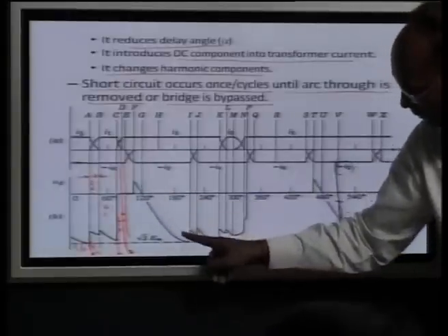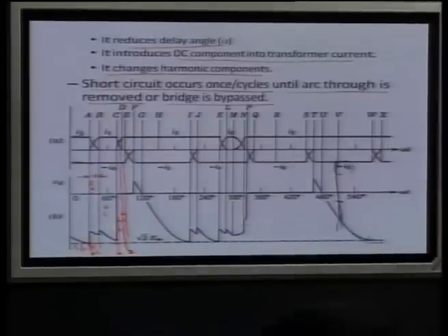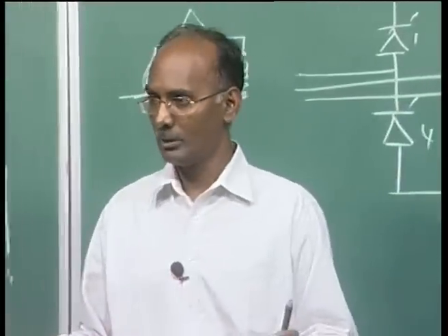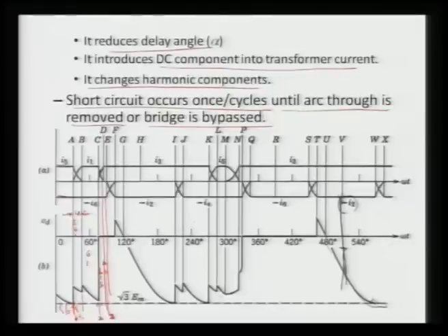Now, this voltage is coming, the positive voltage is appearing across this valve instantaneously, but the average will be negative, because mostly it is negative here. So, I can say at this point, this U period, the commutation between 6 and valve 2 is successful, and once commutation of 6 is over, valve 2 and 3 are conducting, and it will conduct.